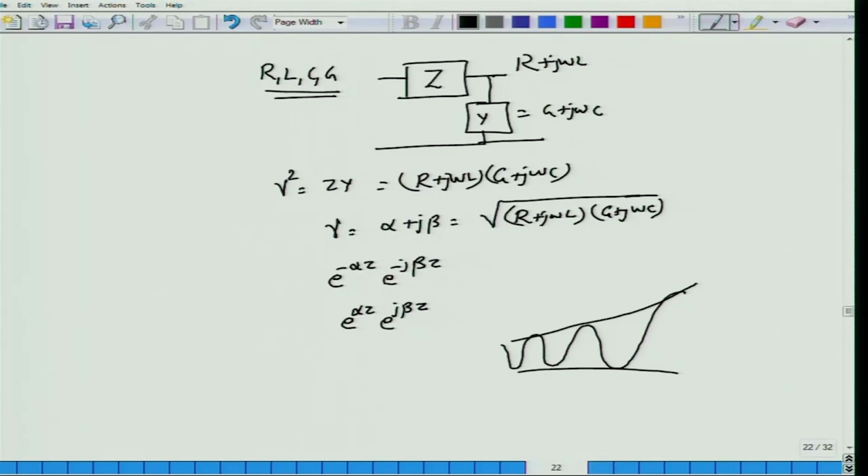We frequently do not really worry about these backward and forward things because the context makes it clear and the signs are taken appropriately as we would like. The attenuation length or the characteristic length L alpha is given by 1 by alpha, and you can be pretty much sure that by 4 times 1 by alpha, most of the voltage wave would have dropped to a very small amount of the initial voltage.